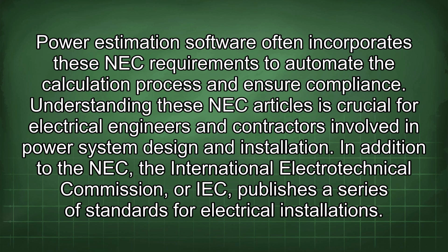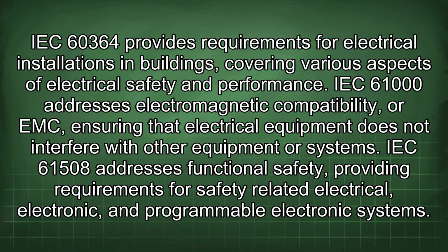In addition to the NEC, the International Electrotechnical Commission, or IEC, publishes a series of standards for electrical installations. IEC 60364 provides requirements for electrical installations in buildings, covering various aspects of electrical safety and performance. IEC 61000 addresses electromagnetic compatibility, or EMC, ensuring that electrical equipment does not interfere with other equipment or systems.